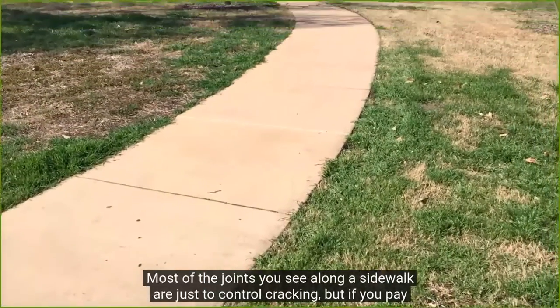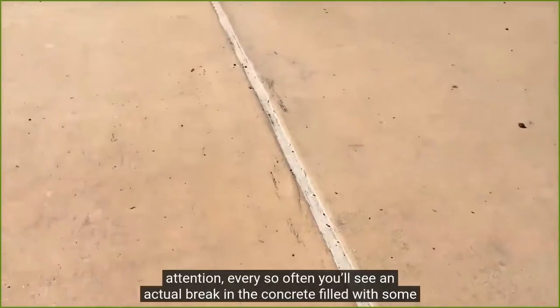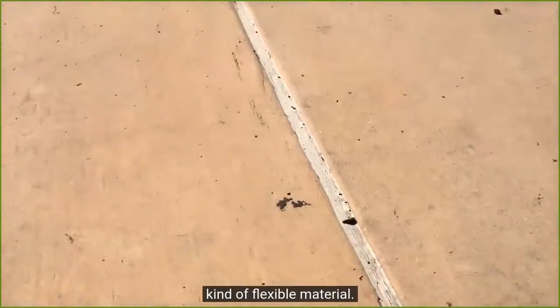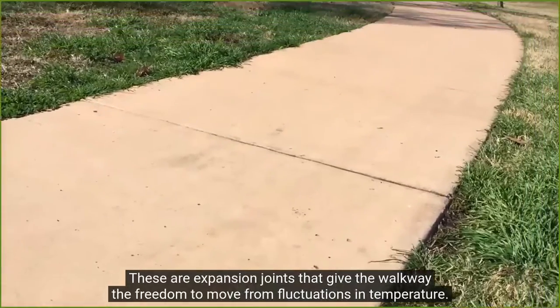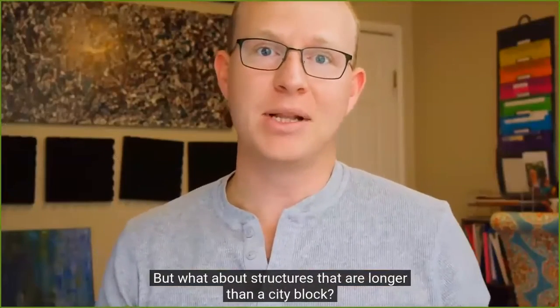Most of the joints you see along a sidewalk are just to control cracking, but if you pay attention, every so often you'll see an actual break in the concrete, filled with some kind of flexible material. These are expansion joints that give the walkway the freedom to move from fluctuations in temperature. But what about structures that are longer than a city block?